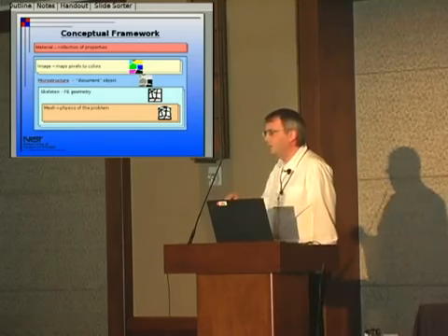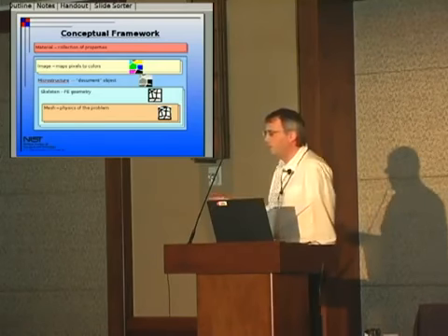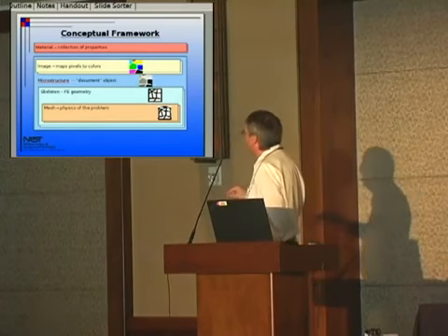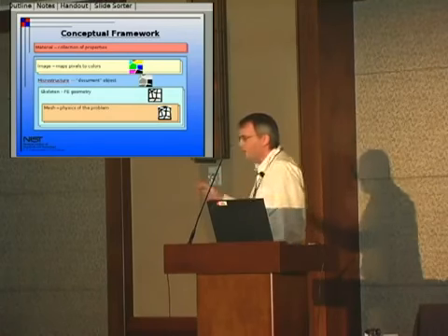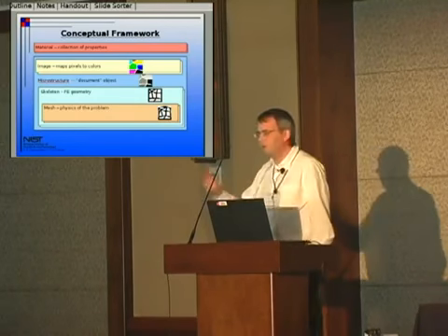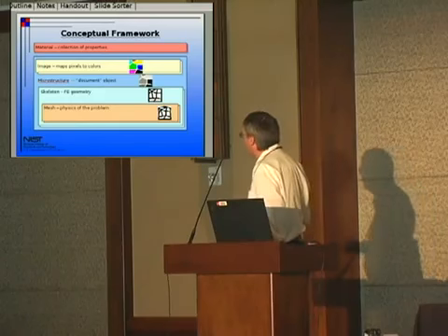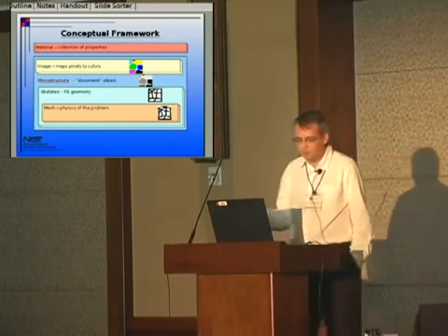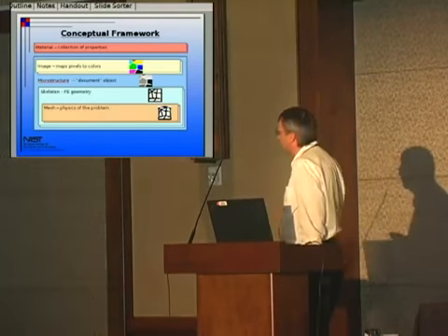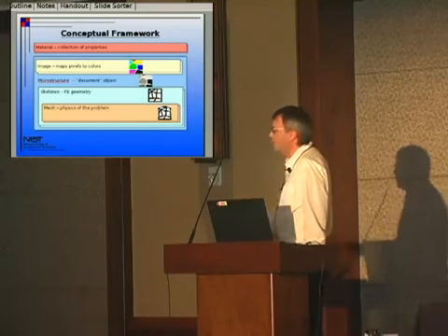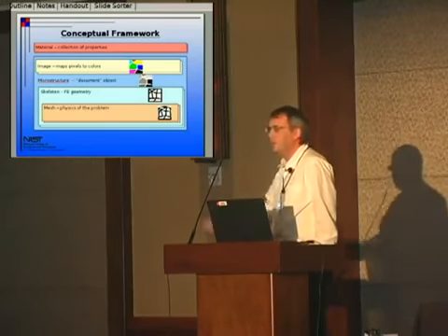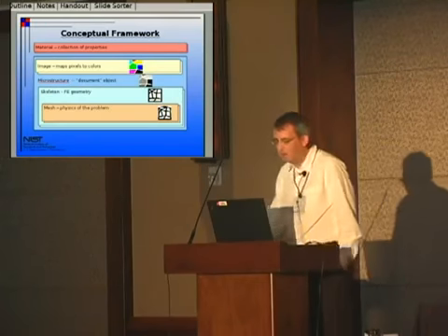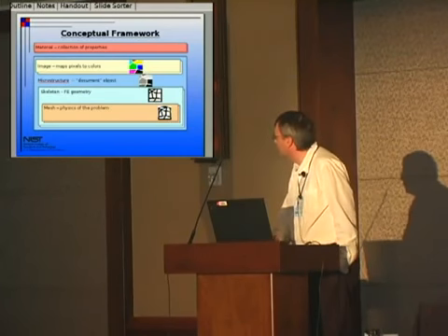That's something that you can manipulate separately, and you can have many skeletons for a given microstructure. And then the actual mesh is the skeleton with the physics, and that's the thing that you can actually do finite element analysis on. And so we find as we go through this that we're overloading terms from time to time. So in the OOF context, for example, a field and a flux and a skeleton and a mesh have specific meanings that they may not have in other contexts.